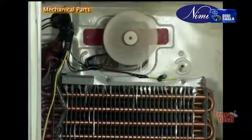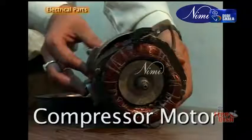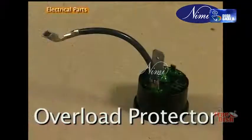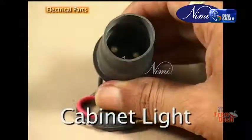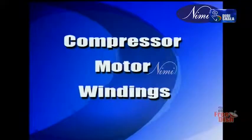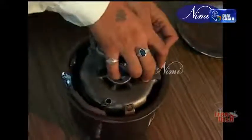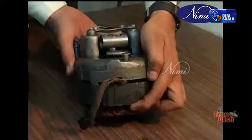into vapors. Electrical parts: compressor motor, relay (ampere type, current type), overload protector, thermostat, cabinet light, door switch. Compressor motor windings. Any single-phase induction motor is not self-starting. It requires additional torque to rotate the rotor. To provide additional torque, a starting winding is necessary.